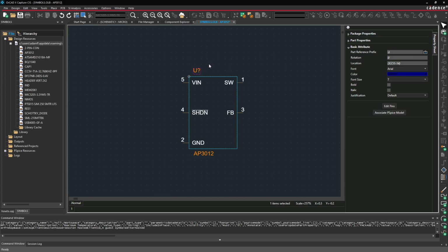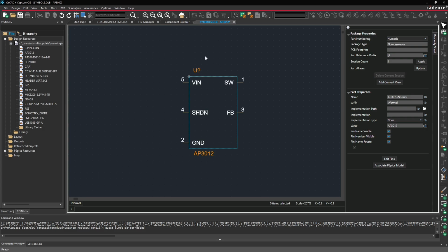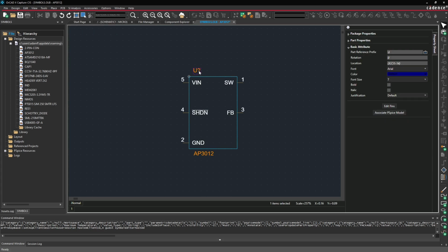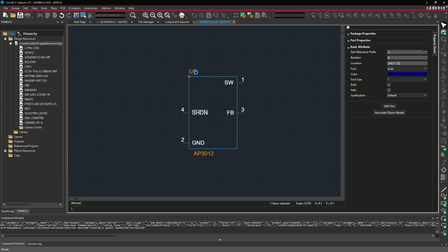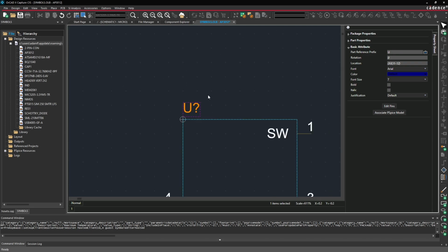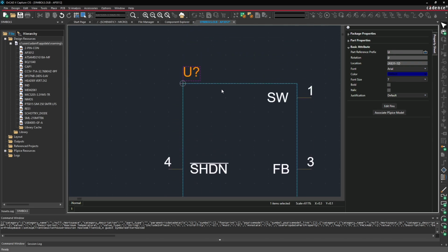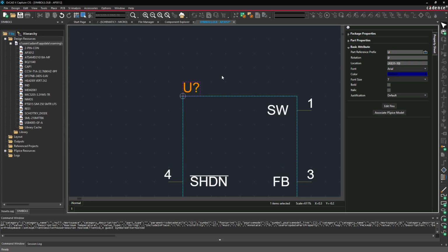If you want to be placing objects and things on the grid or snapping to the grid, you have some grid snap options in the top left here. You can click those, and then you'll have some different behavior on how your pins and rectangles and things like that get moved around and placed. If you want to turn snapping back on, simply click that, and then you should be able to move. In this case, text doesn't follow that behavior, but things like lines and drawing this rectangle will follow that snapping behavior.